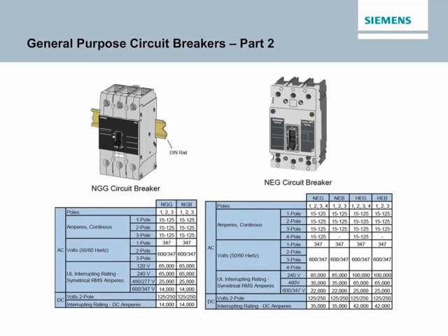Type EG and EB circuit breakers are also 125 amp frame breakers that are smaller in size than comparable type ED circuit breakers. These breakers carry an N or H prefix dependent upon their interrupting rating. N is normal, H is high. EG circuit breakers can be mounted on a DIN rail with an adapter base or held in place by mounting screws. EB circuit breakers are intended for use as branch circuit breakers in Siemens P3, P4, and P5 panel boards, and the distribution section of Siemens switchboards.